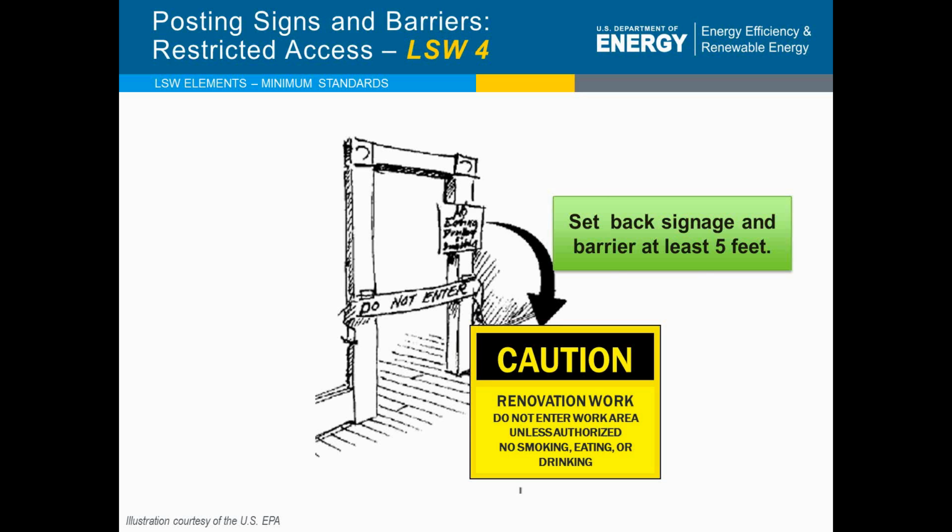I'll list four instances that I've seen in the past. Prior to the refinement of the swabs a couple of years ago, you could get a false negative off the sulfates that may be in plaster and in gypsum. The other is just poor preparation of the sample. You haven't exposed all the layers of paint in a way that the swab is picking up lead from it and reacting to the liquid. And then a swab that has been ruined by excessive heat or freezing.